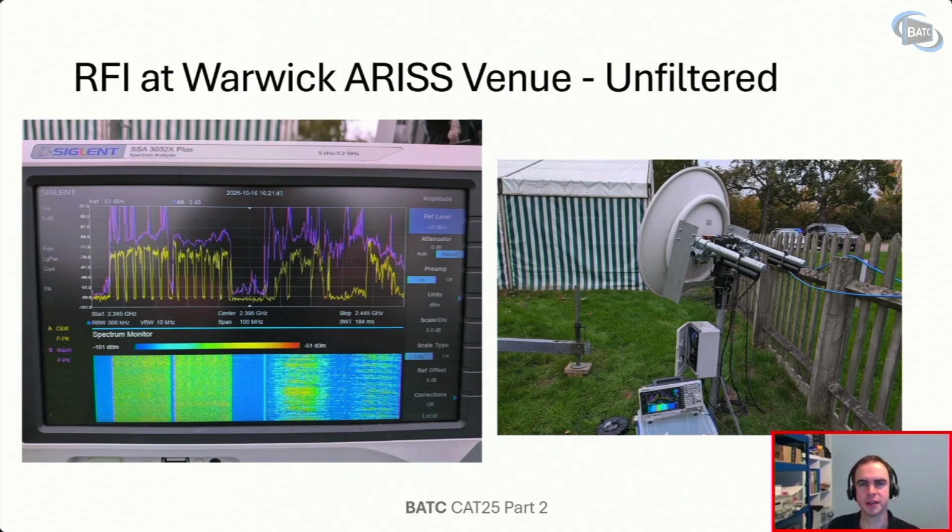And this was particularly looking in the direction of the west, where we're going to start to get the ISS rising over, and where we had fewer ground stations out in the west. We have more to the east. So this is where I wanted to try and optimize it, and there was a 4G tower roughly in that direction. You can see quite a lot of noise coming in on the 4G, and this was causing issues. Particularly the Pluto was seeing bouncing interference in the HAMTV band.